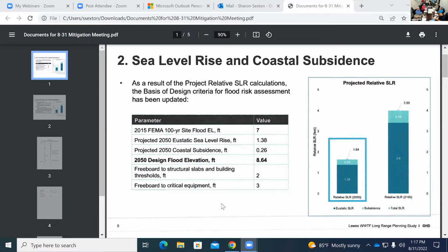And in this area, generally the 500-year floodplain is about 2 feet higher. So we'd be in line with that too. It's actually 1.6, 1.8 feet. So call that 2. Right. But I think the 3 is safe if it doesn't cost BPW a lot. We're still where we were before, basically within inches, a foot higher basically, which I don't think adds much, given the fact that you're building a pump station.